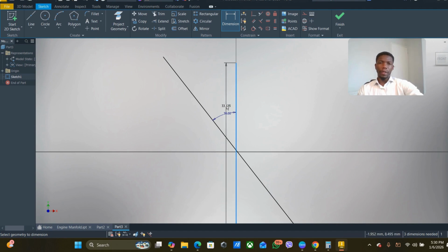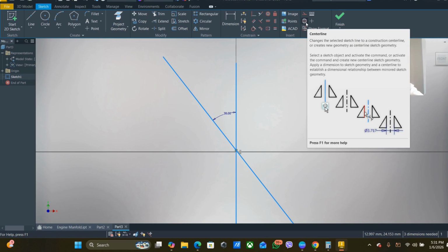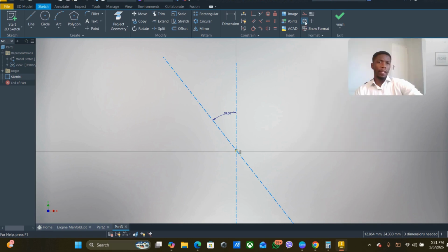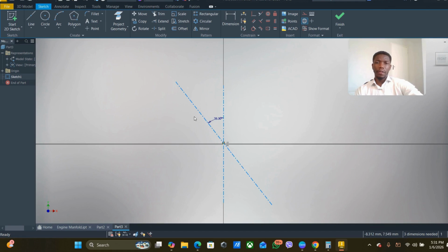The way I do that is by selecting each line, left click, but you need to make sure that you press Control or you left click so that you can be able to choose to highlight the lines, double lines like that. Right, and from there, you're going to go to this little button here that is called the center. You see the center line here, left click there, and you're going to see that the lines are going to change into center lines.